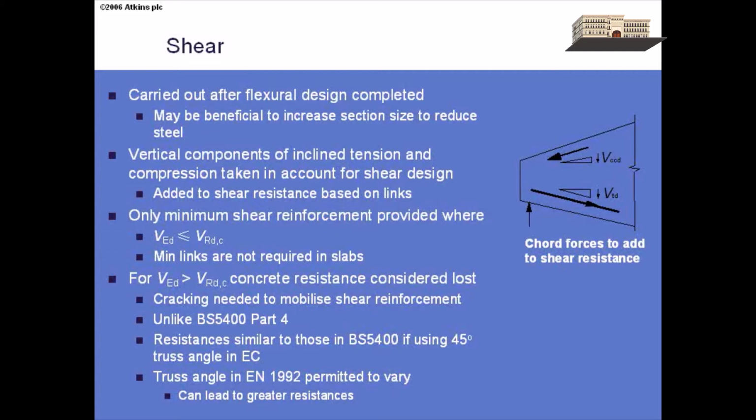For example, when we're carrying out our shear design, it's allowable to include inclined components of both the concrete stress field and also the reinforcement. If we have a horizontal section, then there aren't any inclined components of either the flange or the reinforcement.